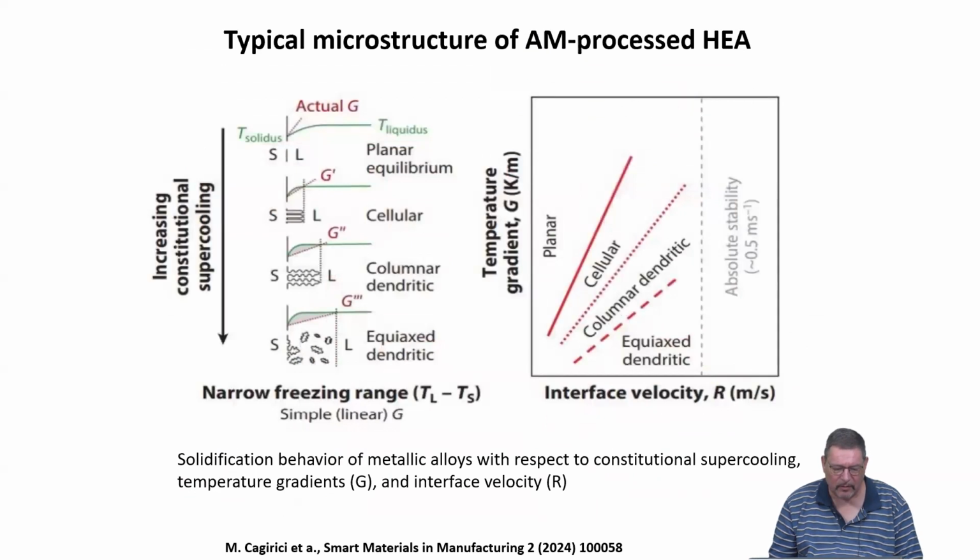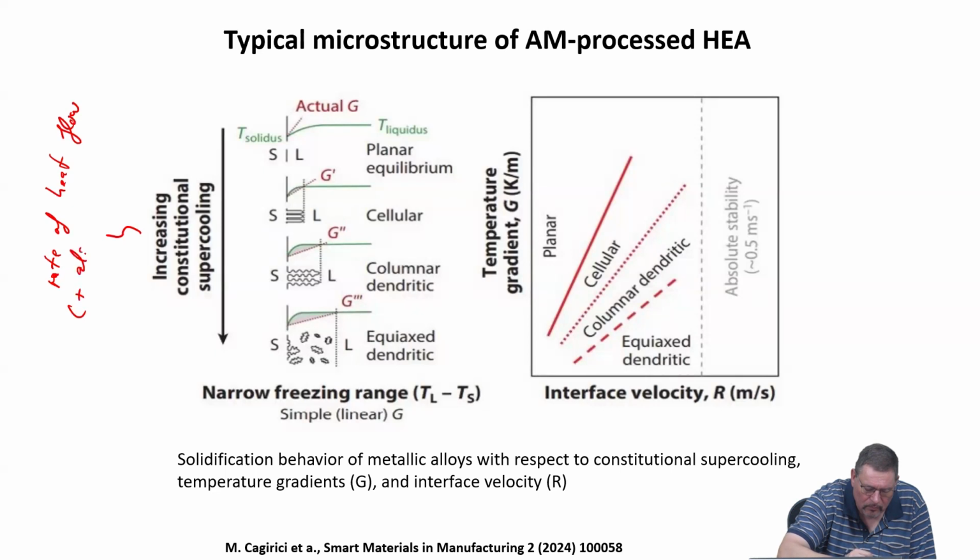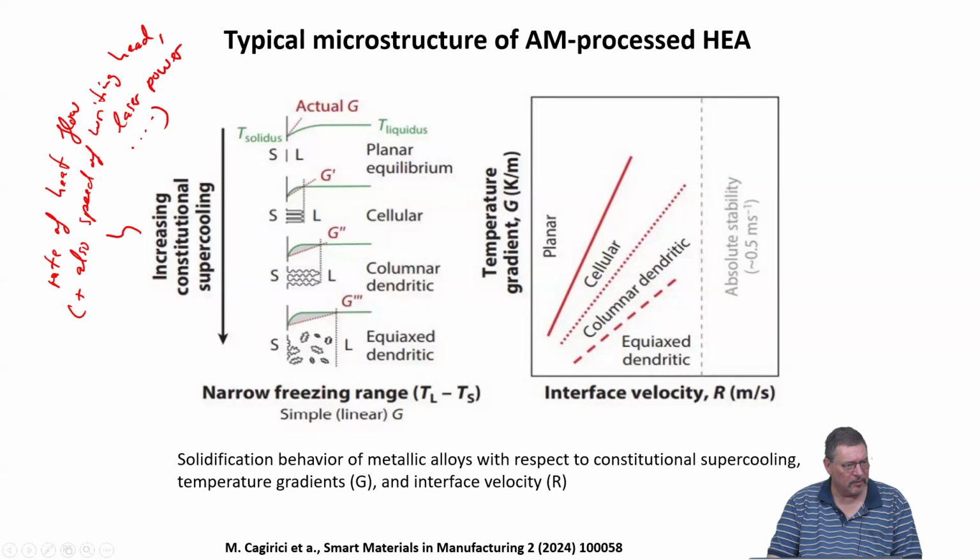And depending on the increasing constitutional supercooling, which is proportional to... So it's really related to many of the processing parameters, like how do you deposit the energy, how much of the energy do you deposit, and how much time you give the system to either melt or cool.